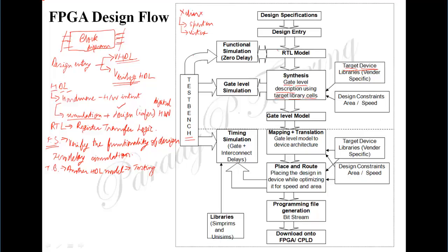For example, if you use an if-else or a case statement, it doesn't make any difference as far as the simulation is concerned, but sometimes it makes a bit of a difference when we go for synthesis. So that's the reason why, while doing synthesis, we may have to see what kind of hardware we are trying to generate out of the code we have written, and that comes with practice. So this is one thing which we try to do with synthesis.